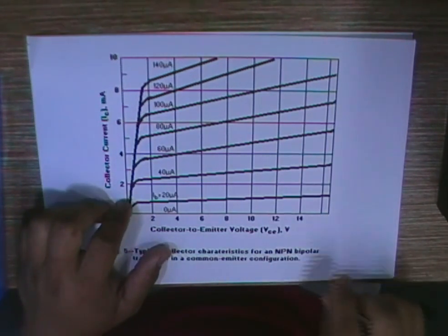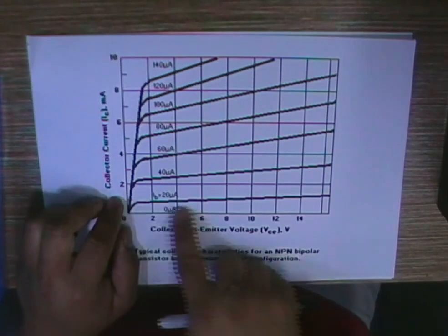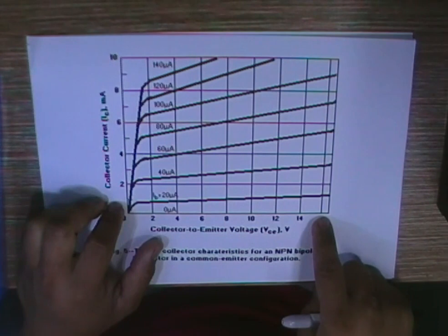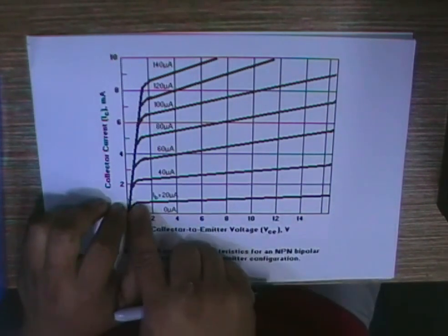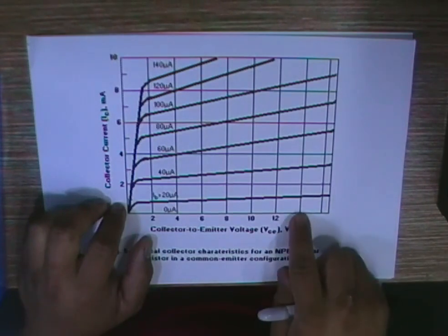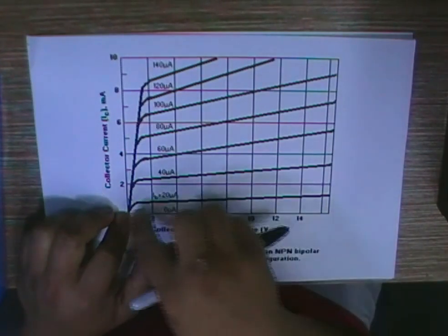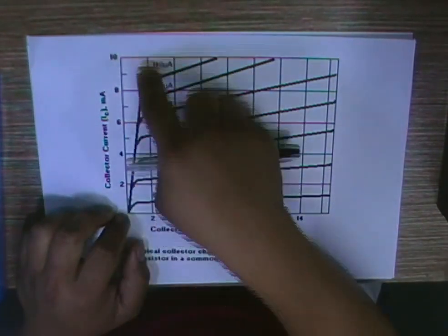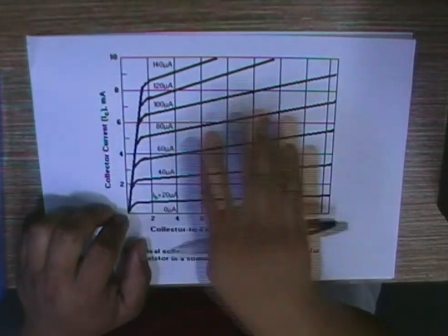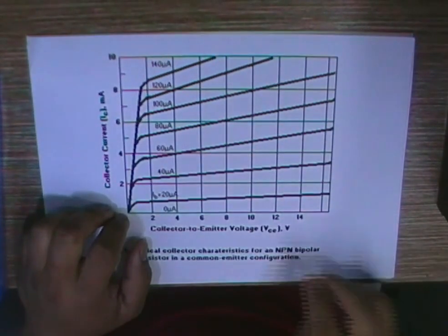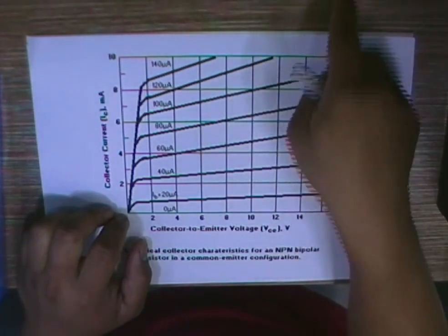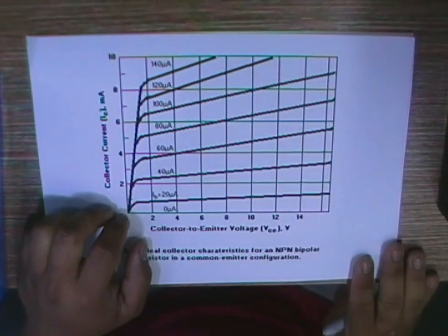The problem is that when you have a very low IC current and you have very high VCE or VCC, in this case, your amplifier will very easily go into the saturation region. This is the cutoff region and this is the saturation region. When your transistor is in the cutoff region, it will be totally off. And you have another one that is not shown in here, which is the safe operating region. So it will go up. We don't care about that.